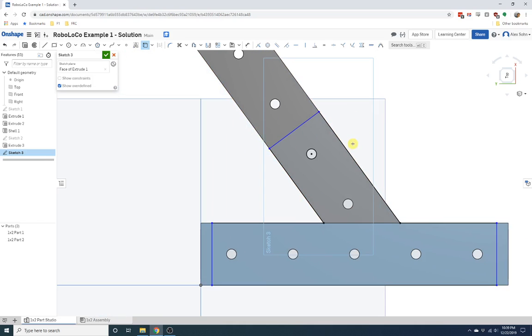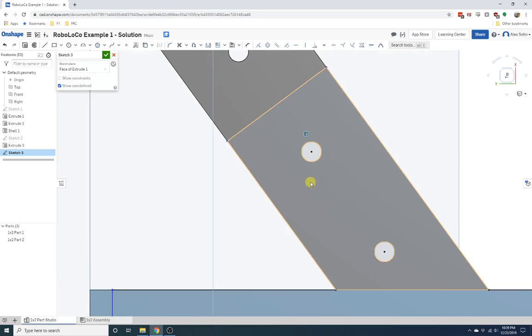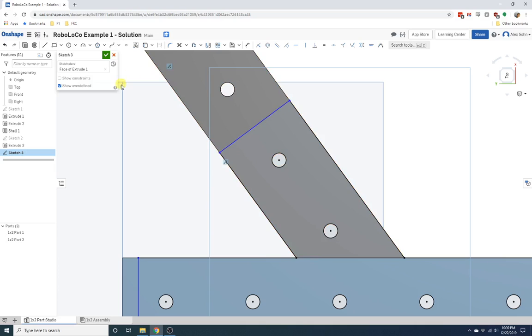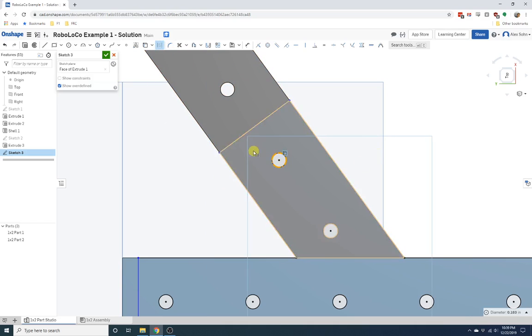What it means when you project is that you project a geometry into your sketch, basically. So I'm going to click all these holes here. Let's just say you didn't want to make those holes, but you wanted to be able to use that reference. I think what you could do is, let's say I click this one and I didn't want to make the hole. I could change that to a construction line. That would allow you to use that geometry, but not actually create any solids from it. So I'm going to turn it back because I actually do want to make that hole.